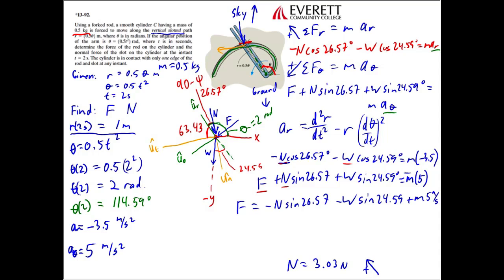So F is equal to negative. And now you can see here we have our normal force. It's important to plug in the negative number that we solved for, because that was in the direction that we used, the direction of the free body diagram, to create this equation of motion. So we have to stay consistent. If we drew the arrow going downwards, we get a negative number. We need to plug in a negative number here.